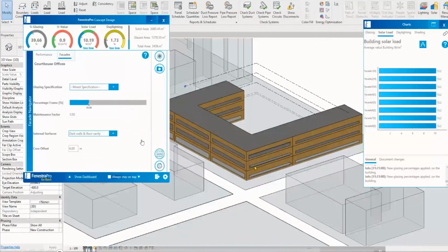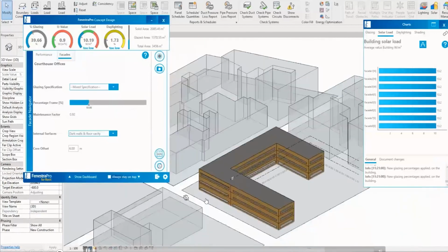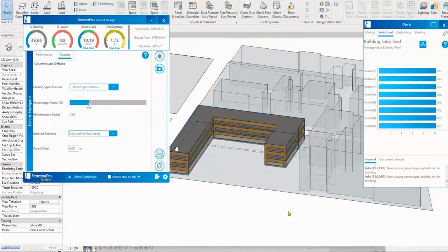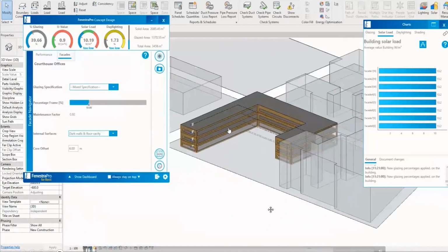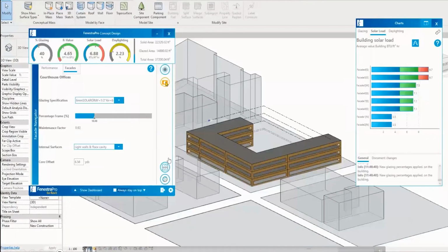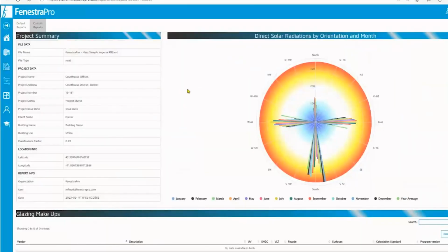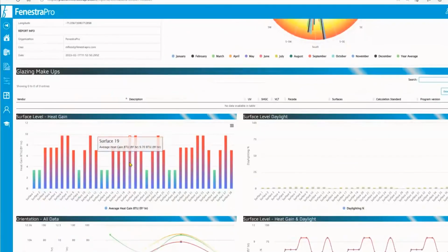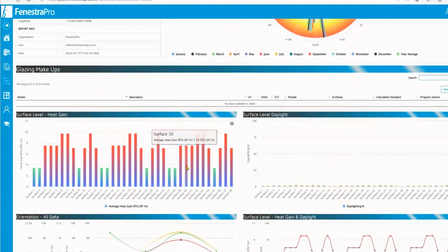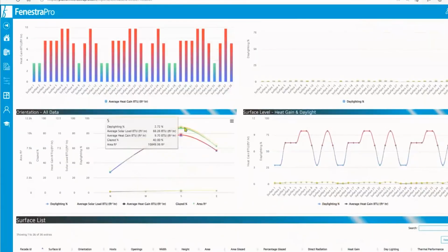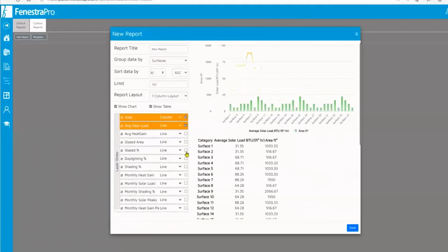Again, we can obviously look at that distribution of glazing, whereby we can equalize the heat gain across all facades, and invariably end up with more glass on your north than you do on your south. And then you can override those considerations for the purposes of trying to achieve aesthetic. You might decide, well, I want close to 100% glazing on my side facade. So you can set that, lock it in, and distribute the rest of the glass to the rest of the building.